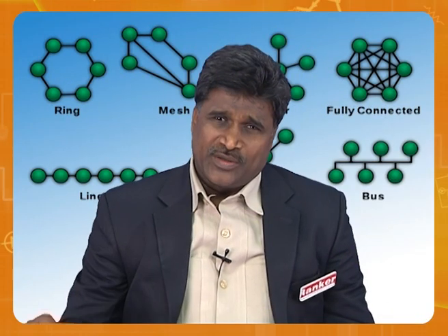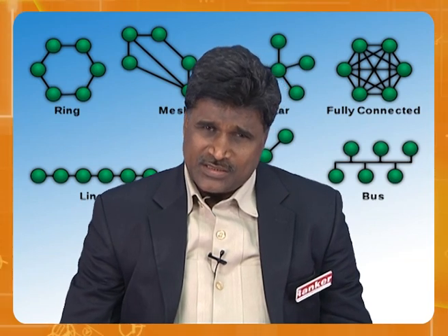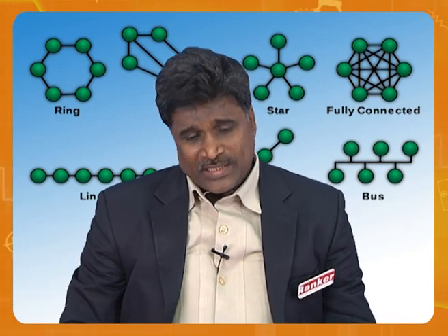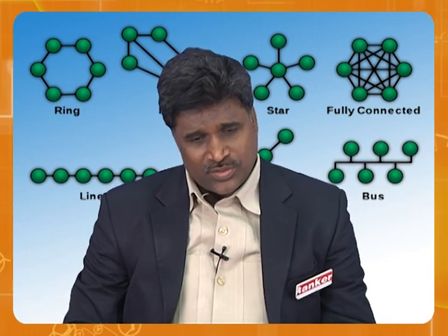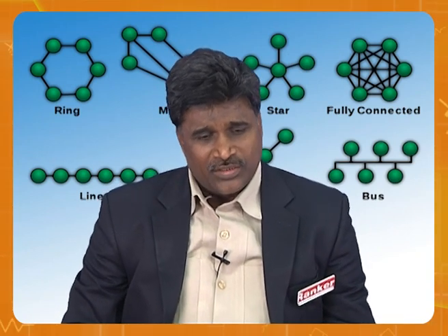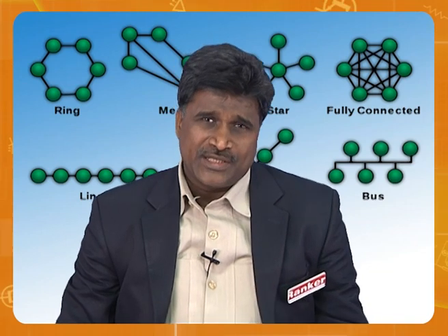As we have been following in KCL and nodal analysis, whenever the current is leaving, we call it positive. The same notation we take here. Whenever it is entering, we call it negative. And we say 0 if it is nowhere connected. So, looking at these 3 simple definitions, we are going to see how to obtain the incident matrix.